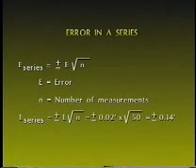This is the product of 0.02 times the 50 lengths. However, random errors have a plus or minus value, and therefore they tend to compensate over the 5,000-foot distance. Therefore, the error in the 5,000-foot distance is less than the absolute maximum error of 1 foot, and in this case is plus or minus 0.14 feet.